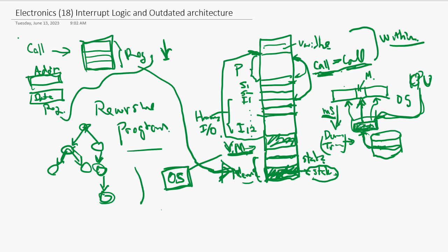You have a communication line going, and here the data fills up the cache, then an interrupt is generated requesting the CPU to get the data, because otherwise when the next connection more data comes, it's going to overflow. Okay, so this is timing critical. So an interrupt has to be processed in the middle of a running program.